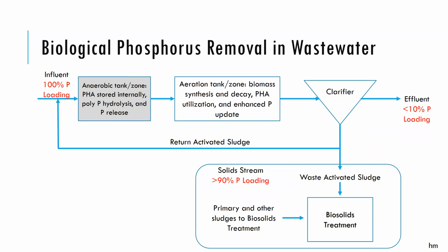And this is just a rough mass balance to indicate to you that of the 100% of P that comes in the door, you're looking to produce an effluent with a very low level of phosphorus, so that most of it ends up in the solid stream, and that then creates the headache because some of that is released during biosolids treatment and then forms the basis of what John is now going to talk about in terms of a side stream treatment technology. Go ahead, John.